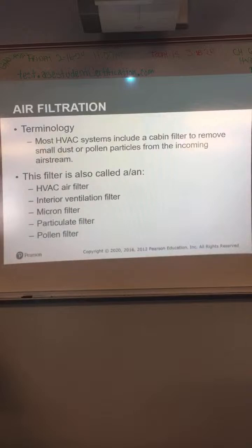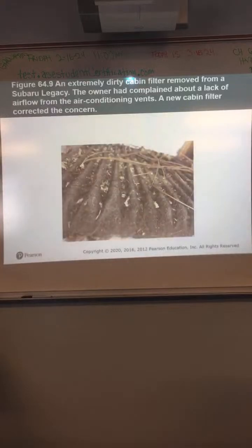The filter is also called an HVAC filter, interior ventilation filter, micron particulate filter, or pollen filter. This is one that hasn't been changed in a long time. Extremely dirty cabin filter. If you find that the air doesn't come out of the vents very hard, even when you got the blower on high speed, that's probably what's wrong.